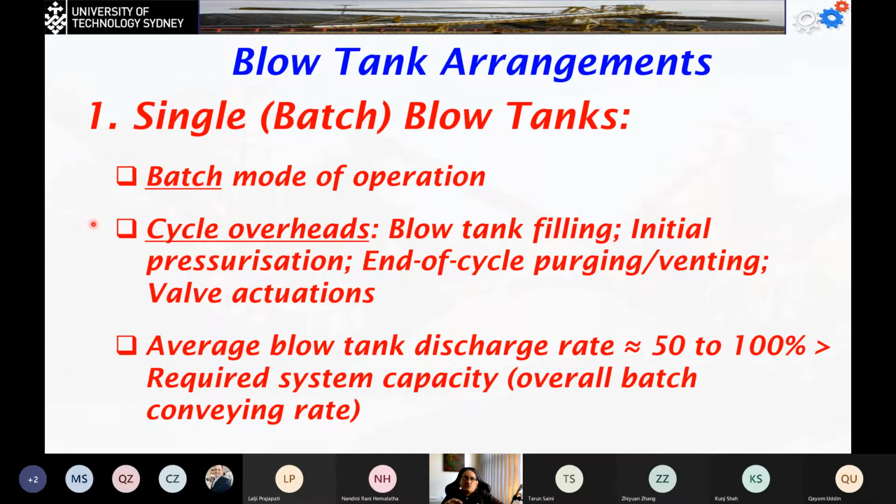Now, I don't want to stop the feeding. Some applications can accept waiting until we fill the tank with the material, and that's if we're going to use a single blow tank. So it's going to be one blow tank, and we feed the material in batches. What happens is that we have the cycle overhead: the blow tank filling, initial pressurization, and by the end of the cycle, we have the venting, filtering, and the valve actuations.